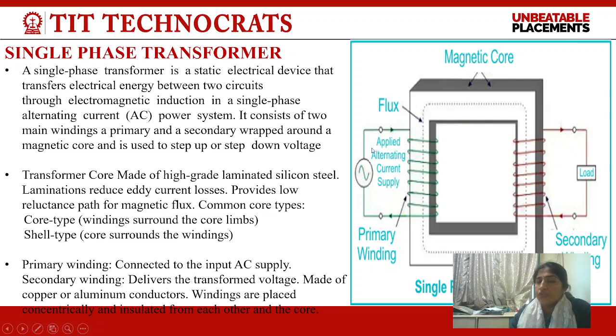So from the overview or pictorial of the single phase transformer shown in the figure, this figure indicates a block of ferromagnetic material. Basically, these blocks are slices of rectangular laminations that are aligned one by another by varnishing with some thick viscous liquid like grease, and they are assembled together.